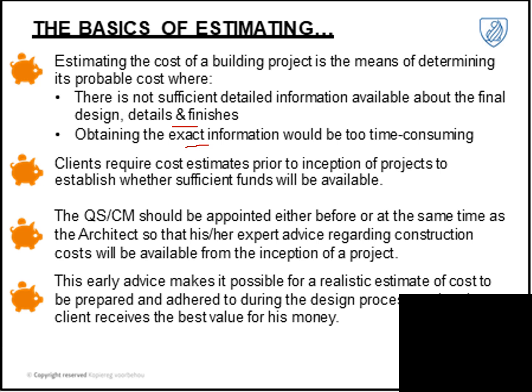If you're working within a company, for instance an engineering company or a design company, you can actually ask for some of those details within your company. Otherwise, you can ask the architect or the structural engineer or some of the civil engineers to provide you with some information that you can work from. For instance, you can work per cube and then a rate of the reinforcing that is actually applied, in the range of 120 kilograms per cube of concrete, for instance, for reinforcing. So you can include items like that, but that is really subject to what information the consultants can provide to you. Hence, we do use the single price methods, which include this information at early stages of the project. The client requires a cost estimate prior to the inception.